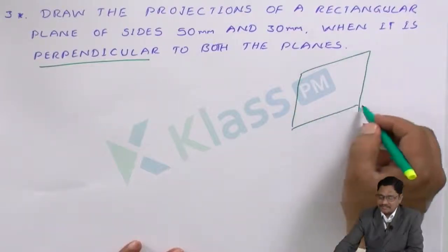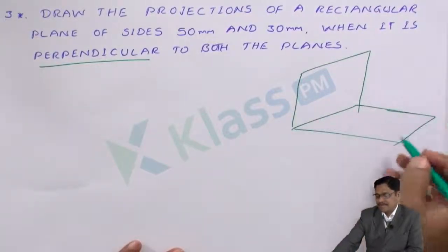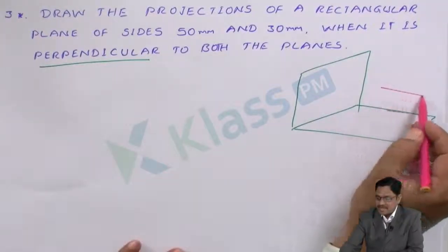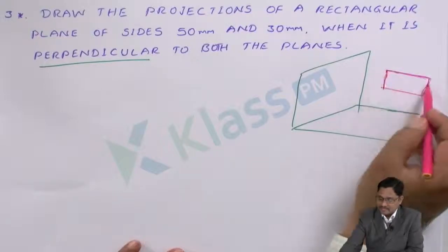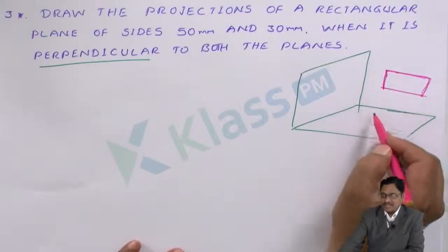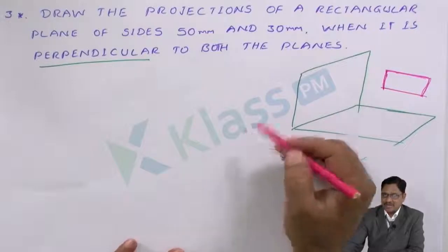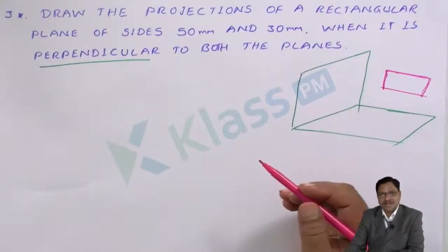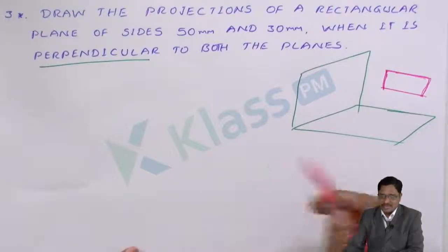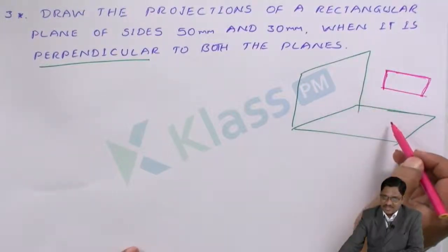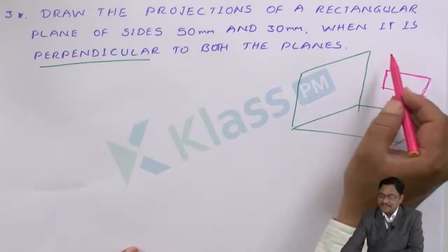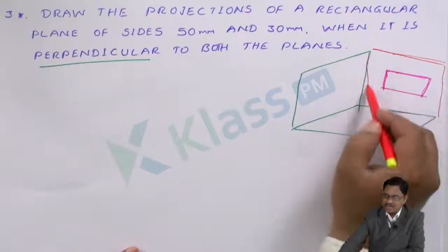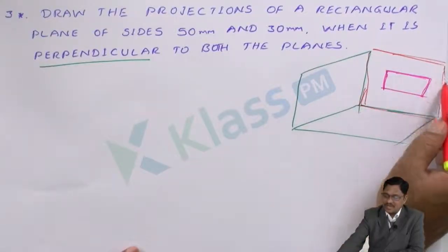Now these are the planes of the given quadrant, HP and VP. As per the condition, the plane is perpendicular to both HP and VP. There is no true length that can be identified. But I can initiate whenever there is a parallel, then only can I get the true shape. So for that, instead of these two planes, just imagine one more plane which we are keeping, perpendicular to both the planes. This is known as a profile plane.